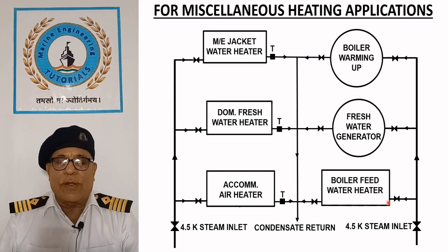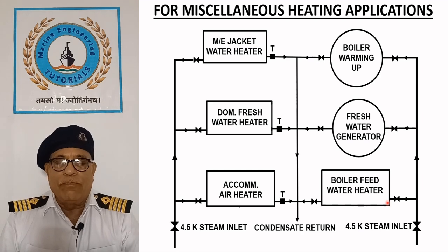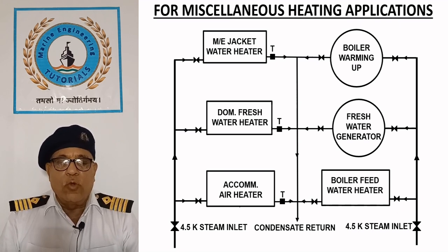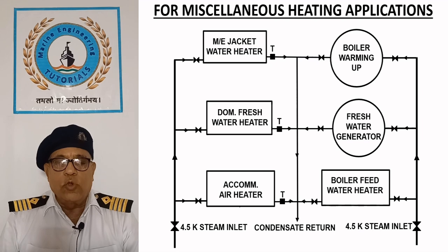Boiler feed water heater. The hot well is usually fitted with heating steam to warm the feed water, which reduces the thermal shock to the boiler and removes dissolved gases like oxygen and carbon dioxide to prevent corrosion.